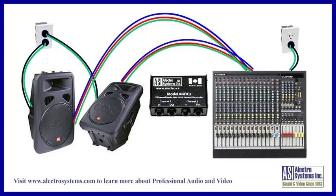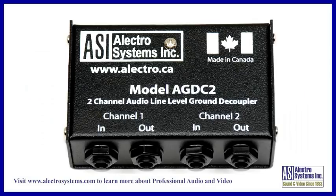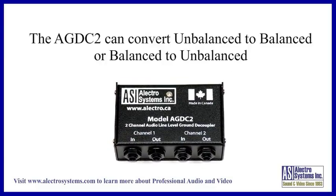This is done with an AGDC2 line level decoupler. Like the DI box, it breaks the ground connection between the inputs and outputs and fully isolates the inputs from the outputs. The AGDC2 is a two-channel device which can be used for stereo or two separate mono sources. All the inputs and outputs will operate as balanced as well as unbalanced. This allows you to convert unbalanced inputs to balanced outputs, and vice versa. Electrosystems makes cables to connect any line-level audio source to any line-level audio destination through this unit.